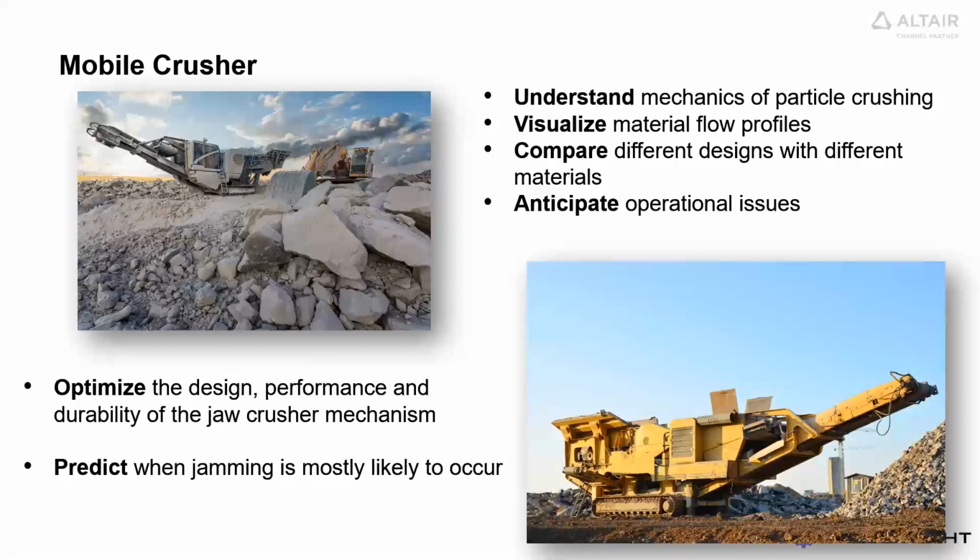Shifting to a different application, another application for EDEM is mobile crushers. EDEM can be used to understand the mechanics of particle crushing and the spatial distribution of wear on a liner. By understanding how the bulk material interacts with the crushers, it's possible to optimize the design, performance, and durability of the crusher.